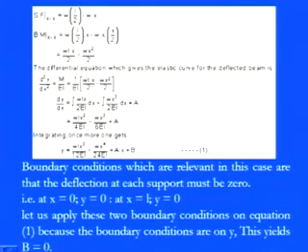Since it is a simply supported beam, it is going in the sagging way, so as per the sign convention it comes as positive. So either the shear force or the bending moment is supposed to be positive as per the sign convention which we have used. So the bending moment at section xx is equal to WL into x divided by 2 minus Wx squared by 2.